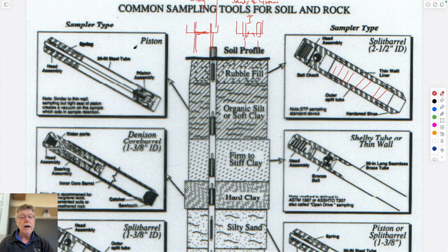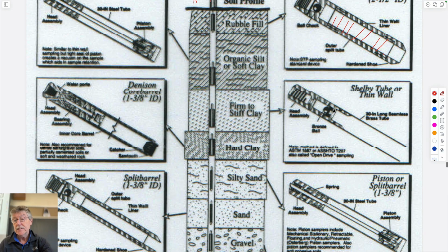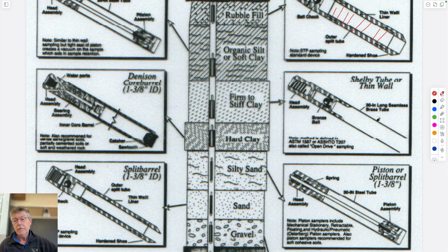So two kinds, thin wall samplers, thick wall samplers, sometimes with fancy things like a piston in it to be able to make sure that you get recovery. I guess this is a thin wall sampler. You can see the difference between the thickness of this wall and this wall. And this is just a piece of plumbing, when they used to plumb houses with a brass tube, probably 4 inches in diameter. And this one has a check valve so that if it's a soft, granular sediment, it doesn't get washed out by the water pushing it out.